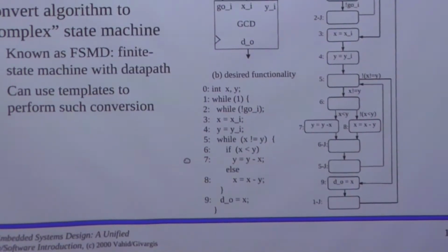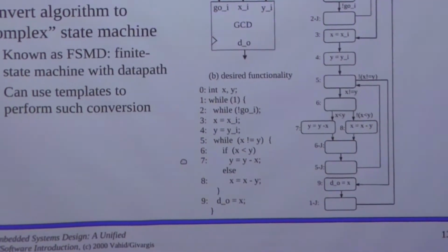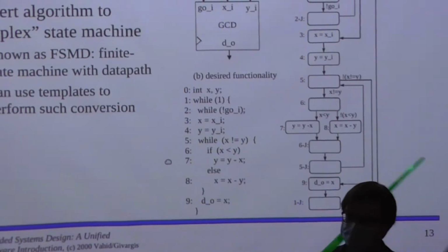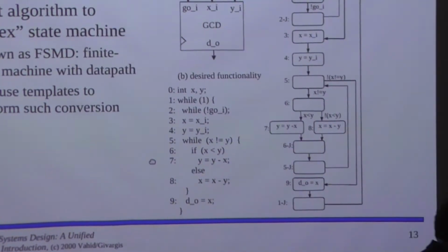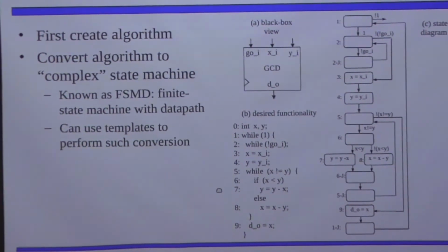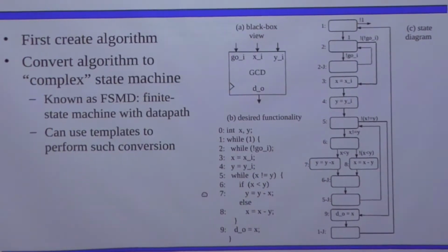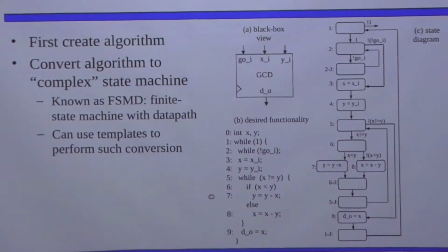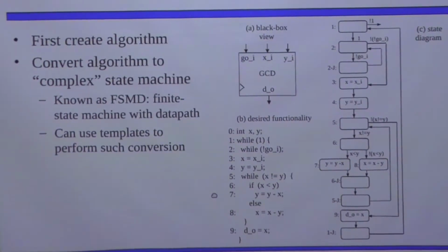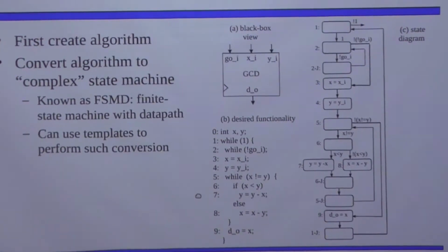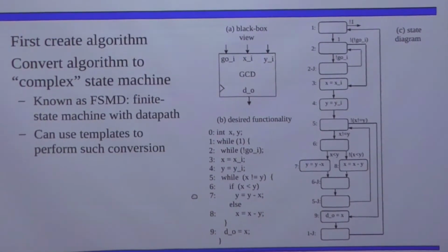Also, it's not a bad idea in general to register your inputs, because by registering your inputs when you receive a start signal, you no longer have to trust that whatever is providing those inputs remains stable for the duration of the calculation. So it uses a little bit more memory, but it's not a bad idea in terms of design stability, if that makes sense. It depends on how much you trust the people you're working with, really.